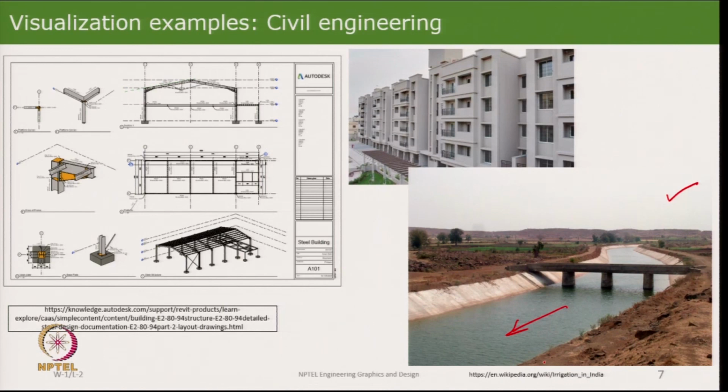So, how do you do this? For that you need to understand the terrain, and then you see where is the source of water and where do you want the water to end up, and then you start putting a line on paper to say, well, this is how I am going to route my canal. And then we go into the detailed engineering to see whether the soil is good enough for that or not, and how the embankments have to be designed, where you need to provide bridges for people to cross, and that becomes the basis for then making it.